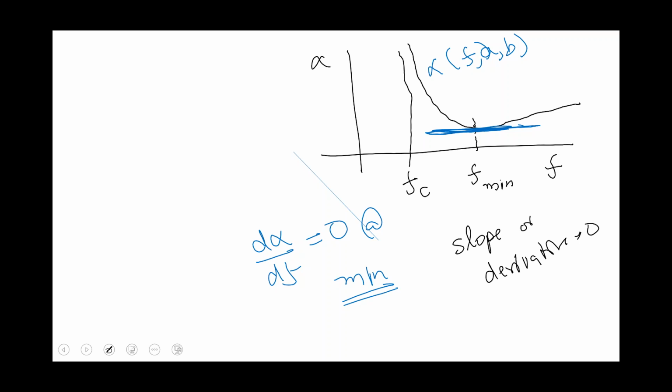So intrinsic impedance for TE is eta medium divided by square root of 1 minus (fc by f) squared. Right? So any term which is present within that attenuation constant which depends upon frequency, you'll have to write it in terms of frequency to be able to take the derivative.